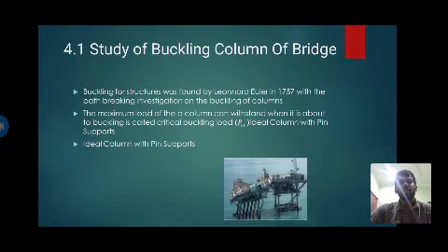Ideal column with pin supports. The column that we consider is an ideal column, meaning that the column is perfectly straight before loading, is made from homogeneous material, and the load is applied to the centroid of the cross section. It assumes that the material behaves in a linear elastic manner, and that the column bends in a single plane.